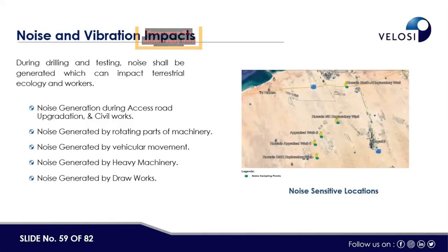Who is the person or authority that monitors compliance in an EMP? Are there any penalties or fines imposed for non-compliance? Yes, basically in every region there is a regulatory authority. In our region, whenever we submit an environmental management plan, there is always a condition from the regulatory authority, the EAD, to submit a quarterly audit report that must be carried out by an external third-party consultant. That consultant carries out the environmental audit, and the report must be submitted to the regulatory authority at minimum on a quarterly, biannual, or annual basis, depending upon the nature of the project.